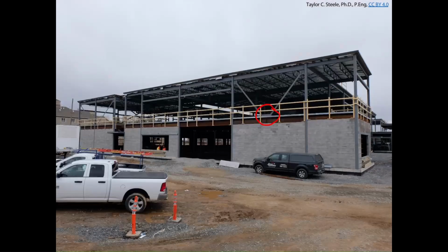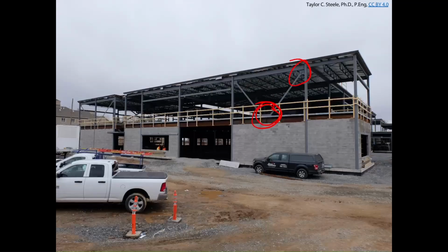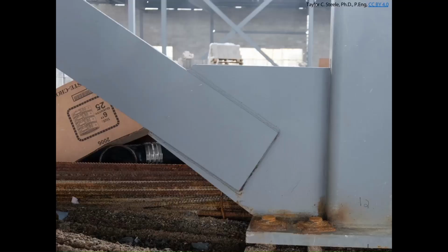I do want to just come back to this example because I had alluded to it before, that in this particular building, the braces were bolted at one end, and due to the procedure they were using to take the slack out of the brace with a pre-tensioning method, they bolted one side, pre-tensioned the brace, and while it had a tension on it, they welded the member at the other end to the gusset plate. So at the upper side, we had a connection that looked something like this, and down here in the middle, we had connections that look something like this.